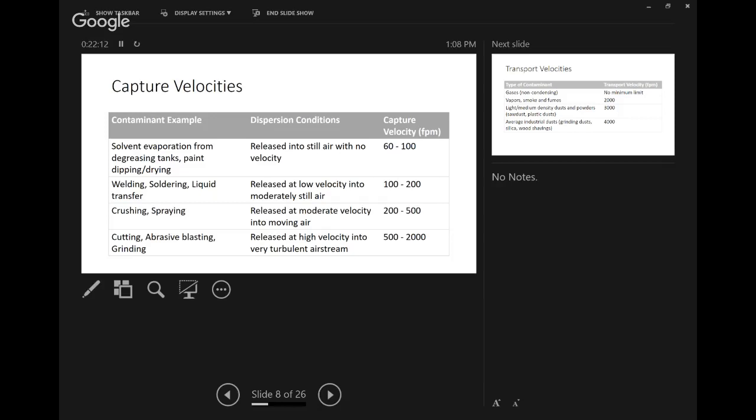And it's this heavyweight bead that is forced through a nozzle onto something at a high velocity to remove the paint while still maintaining the metal finish and not damaging it. And the takeaway is it generates a lot of dust.